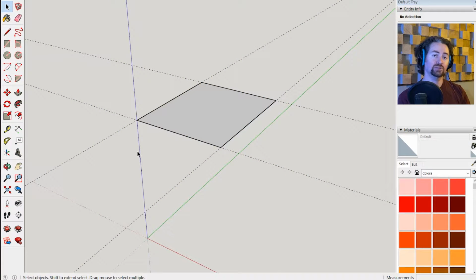This could be based off of the style that you want or based off of your materials available. If you have 1-inch lumber available, make it 1 inch thick or 7/8 of an inch so you can plane it down to your size. I'll make this tabletop 1 inch thick based on the availability of 1 inch thick pieces of plywood.